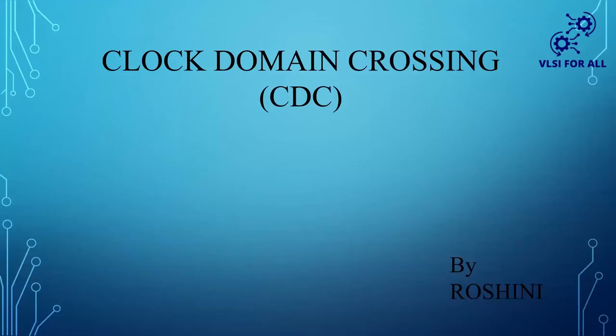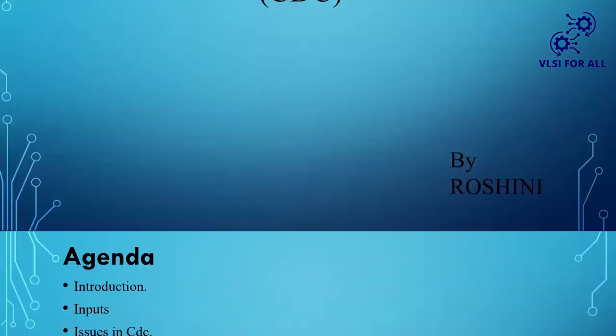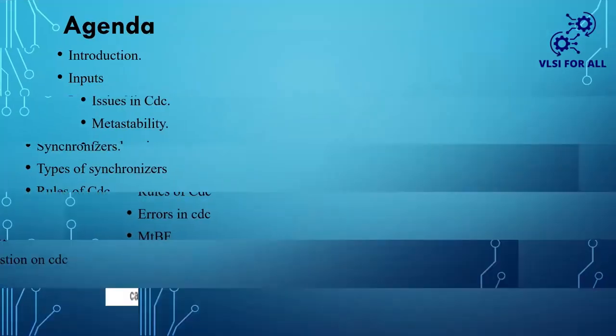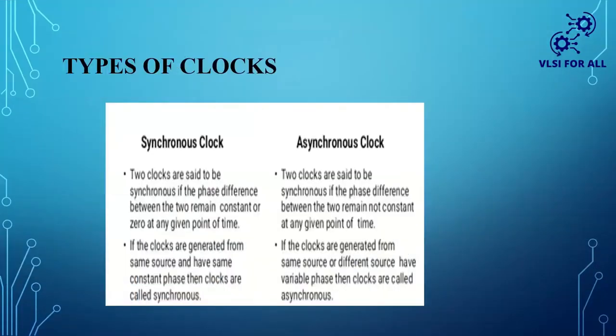Yes, previously I was giving an introduction regarding CDC. There we have learned what a CDC is, what issues we get in a CDC, and what metastability is. And to avoid metastability, we are going to use synchronizers. In that, I explained one example, the two flop synchronizer, and then I stopped.